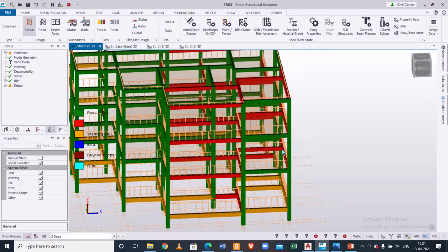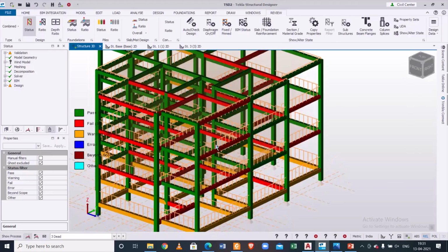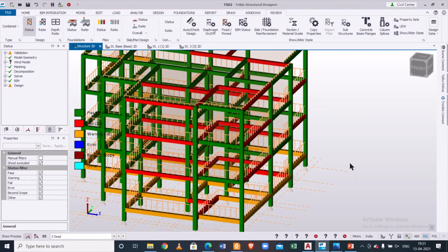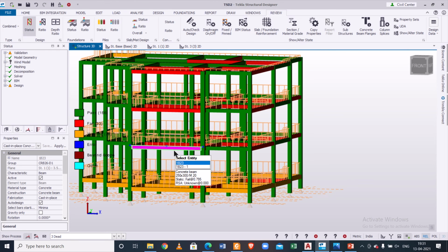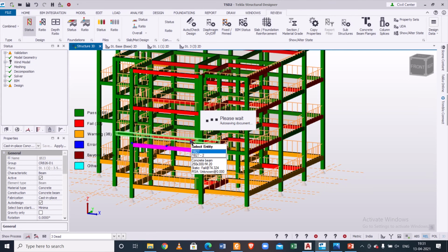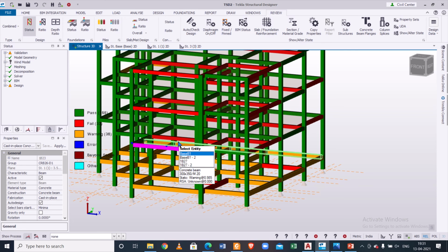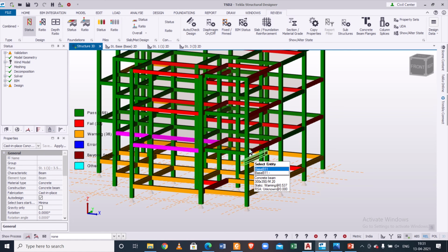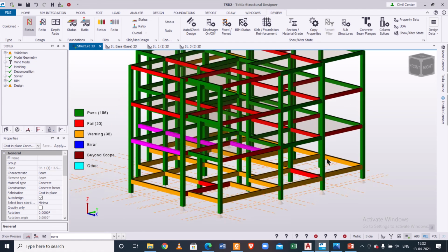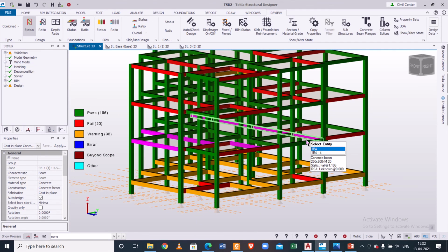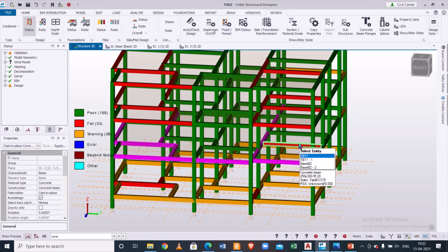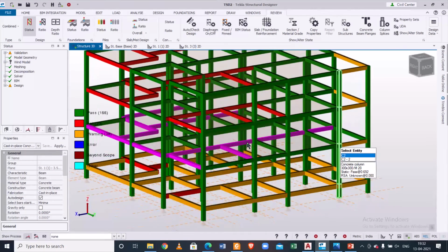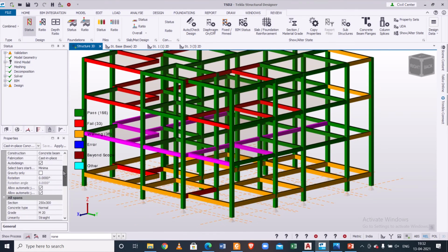And for the beams which are failing, we can increase the size also. Let's go with the beams of one section, because all the loads, as you can see, are the same. So if you make the beams of one particular floor pass, then the remaining will automatically follow. Just turn off the loads here, and this one as well, this one, this one, and this one.